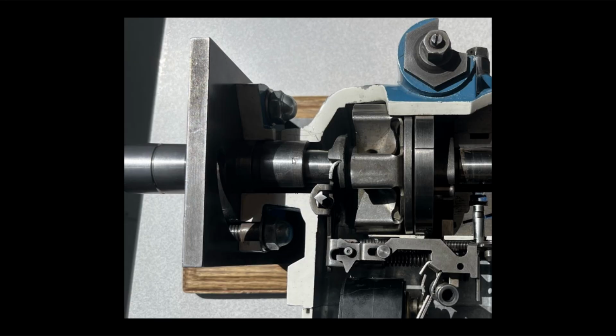In our specific injection pump, the throttle is mechanically linked to the metering valve, which holds the spring tension that the governor fights against. Same concept: the operator depresses the accelerator, moving the metering valve into an increased fuel position, thus increasing your engine speed. Due to the speed increase, centrifugal force moves the flyweights outwards. A balance is achieved by the counteracting components, and therefore stabilizing engine speed.